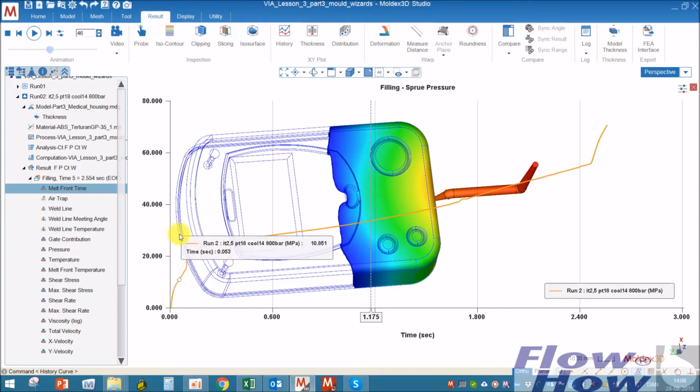And the injection pressure is a result of that you try to push the melt into the mold with a certain velocity, a constant velocity, and if you do that, there's a pressure against this, and it's actually the pressure against this that you have to overcome, and therefore you have to apply pressure out here. The only place you can apply pressure is at the end of a melt.